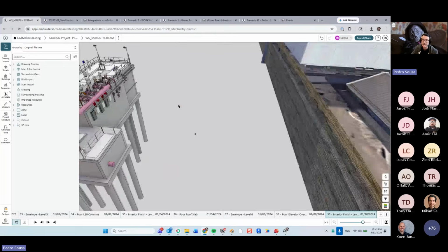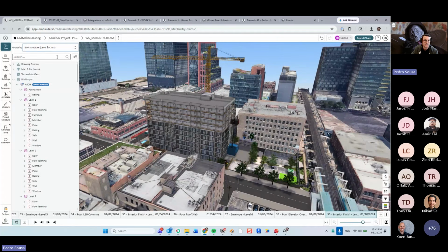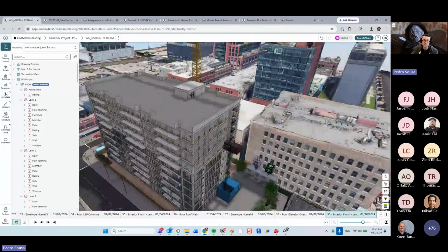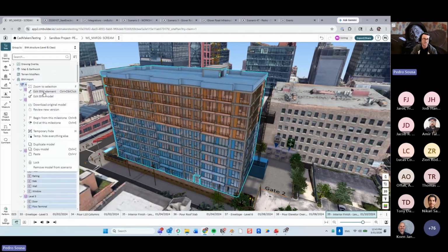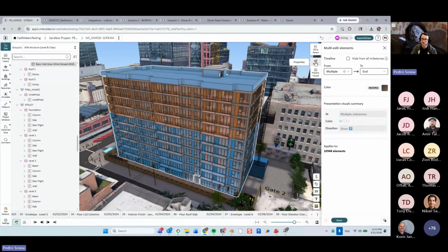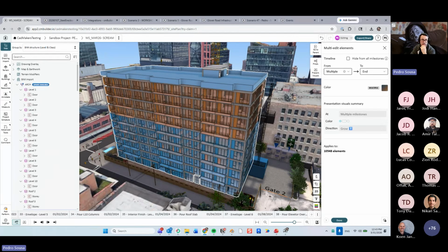Cool. And a quick tip before we move forward is that for IFC and Revit files like this, where you can find a BIM structure pretty well defined over here, let's say that you want to remove all furniture in this model. You see that there's furniture over here. There's no furniture in any of the levels, but there are some flow terminals over here that I want to remove and so on. So instead of expanding this structure and then holding control and selecting each one of these groups, what you can do is select the whole model, go into edit BIM elements, and then go into the properties over here where you can adjust the properties of the parts that you selected. And I can now create a temporary level. So when I do a temporary level like this, basically I'm going to combine all of these parts under a specific level attribute. That's going to be my